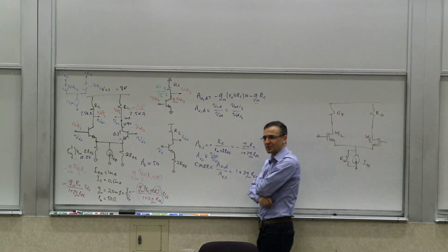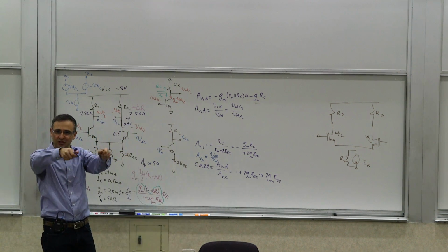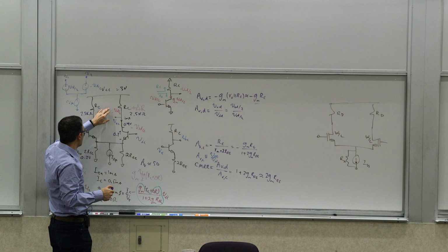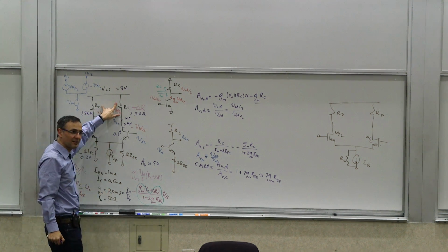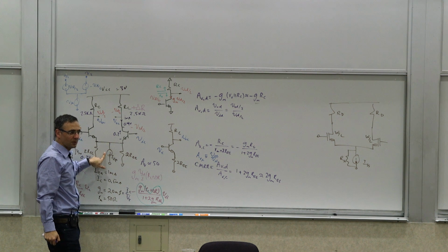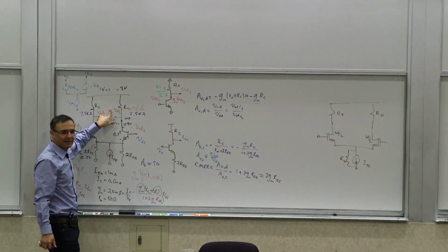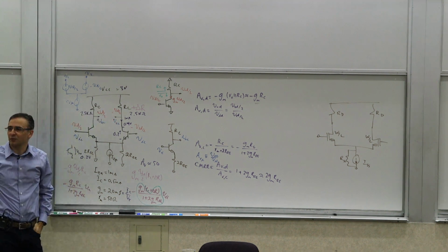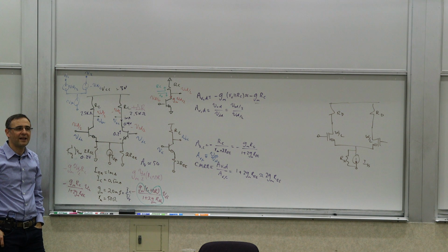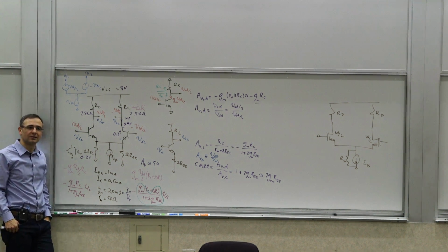You have two choices, right? You can of course take it anywhere on that spectrum of changing one, turning that knob, right? So we had one with 1 milliamp at the tail, 2.5 kilo ohms here, and we had one with, I don't know, a quarter of a milliamp here, and then 10 kilo ohm here. And they have the same differential gain. Is there any benefit, advantage or disadvantage to either one?